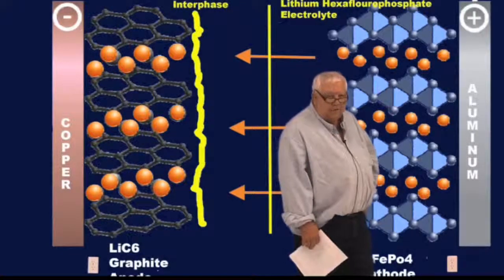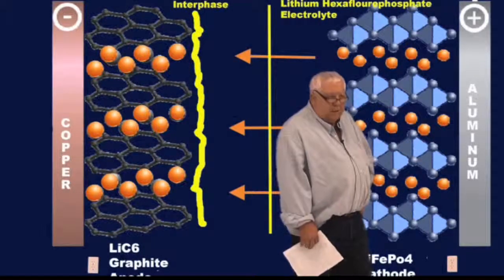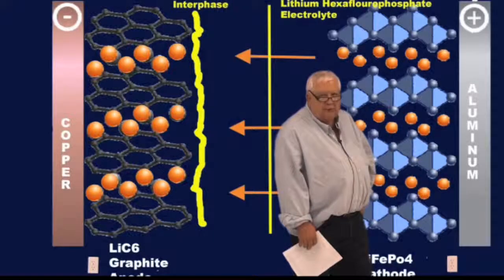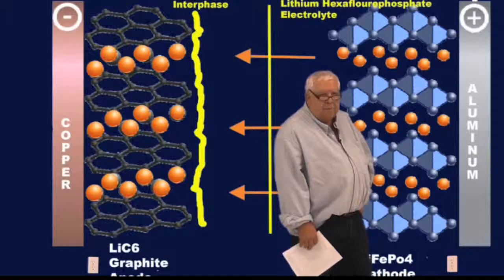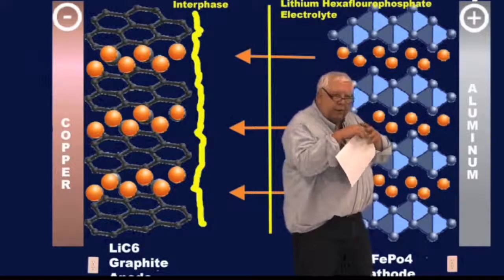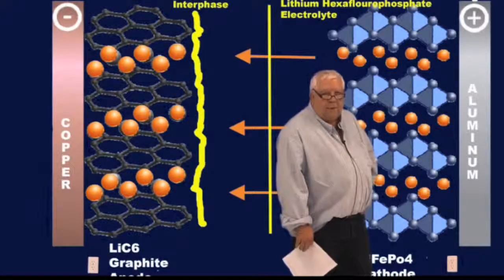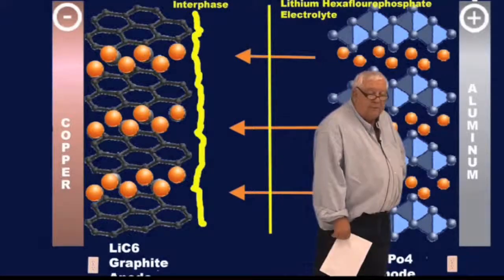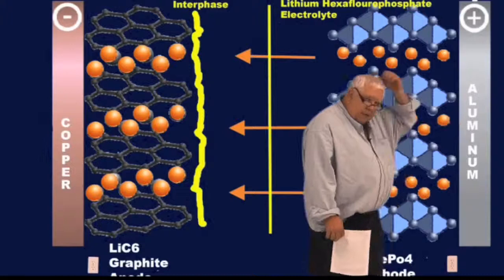So these are very small pellets of lithium cathode material, lithium iron phosphate, and they coat those little pellets with carbon. And so you have to go through the carbon to get to that, which is no problem because the carbon is, of course, permeable to lithium ions, but it's also a good conductor. And then we mix that with a binder and put it on the current collector.